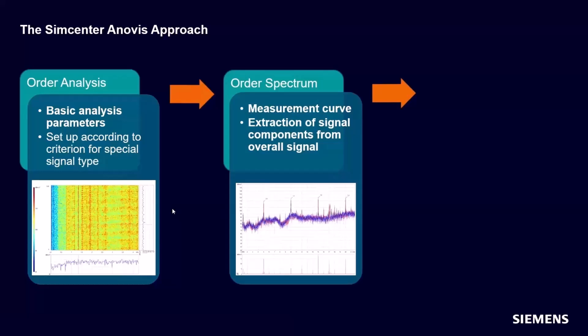As Steph told you before, there are some signal types that are very well visible or analyzable in the spectrum domain, others are not. So we choose the right method here to extract the signals of a certain issue from the complete signal. If we talk about something that is harmonic or that has some modulation or some single frequencies, you've seen before that single frequencies do not show up in the cepstrum, but very nicely in the spectrum. Therefore, we use the spectrum there. Other things like signals with a lot of harmonics are not so easy to identify in the spectrum. Therefore, we use the cepstrum.